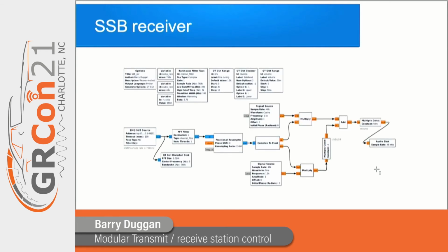The single sideband receiver, this particular module, uses the Weaver method. You've heard of the filter method and the phasing method, and sometimes Weaver is called the third method. And this is it, where actually the BFO is injected into the signals in the middle of the audio passband.